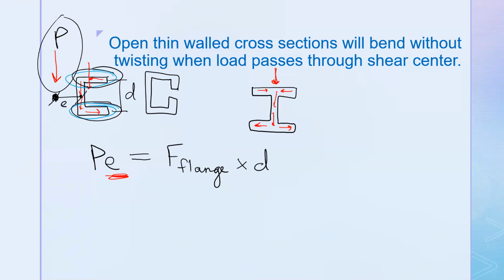So the F flange was the one in the flange, the going sideways, right? Not the one going perpendicular to it. Yeah, the F flange, that's these arrows that are circled in blue, those horizontal arrows. So you might be asking yourself, how do we apply a load that's not touching the member? A lot of times what they do is they put a little angle on the back here, and then the load gets applied on that angle.